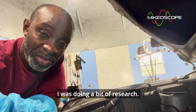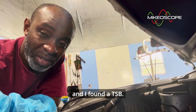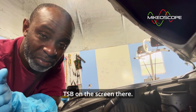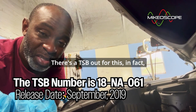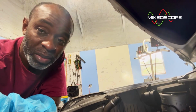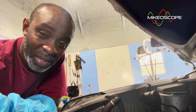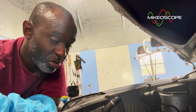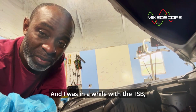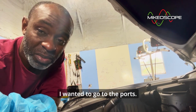I was doing a bit of research. I did a bit more research into this issue, and I found a TSB. I'll put the name of the TSB on the screen there. There's a TSB out for this, in fact, which says if you get a P0411, you should clean the ports. That's something you should do first. So maybe our issue isn't actually the pump like I thought, and I wasn't aware of the TSB, but in any case, when I saw those deposits, I wanted to go to the ports.